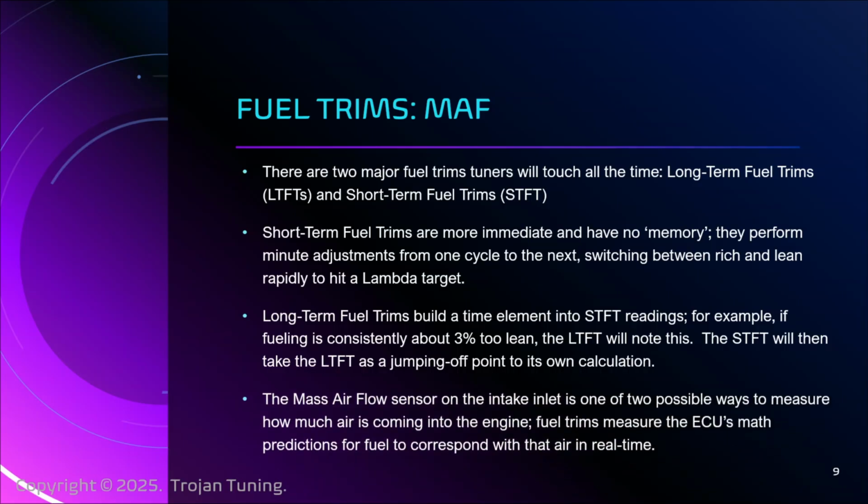And why did we mention the mass airflow sensor? Because the mass airflow sensor is the primary source on the intake of understanding how much metered air is coming into the engine. It knows exactly how much air is coming in. And because the Ford engineers have given us a rich, detailed model of understanding at various points of how much air is coming in, how much fuel we want to spray, we now have a very good sense of what we should be sending in as far as fuel. File that away. If I know how much air is coming in, I automatically know how much fuel I should send based on the model.